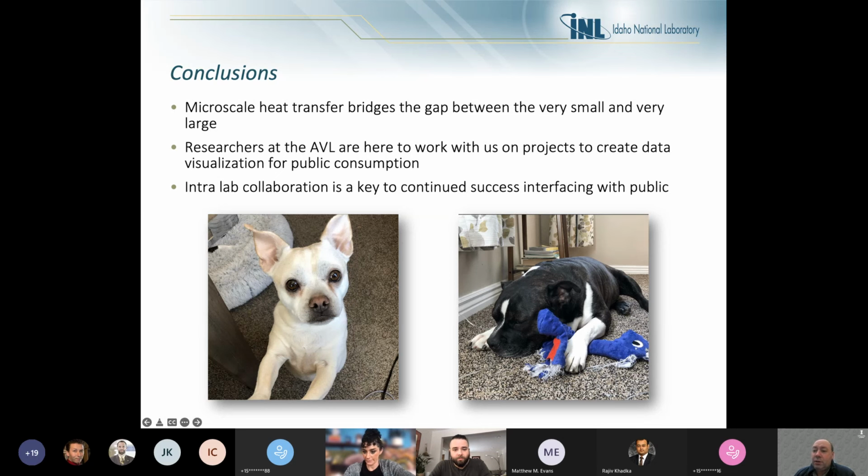Yeah, so what we'll do is, when the material properties get generated for us through DFT or MD, they'll come to us in the 100, 111, 010 directions. It's not really a live thing. They're generated a priori and then given to us to simulate. So a lot of the work, like that graphite, was done in 111. I think the UO2 was as well. But you can do it. It's just a matter of having the data generated for you in those directions.